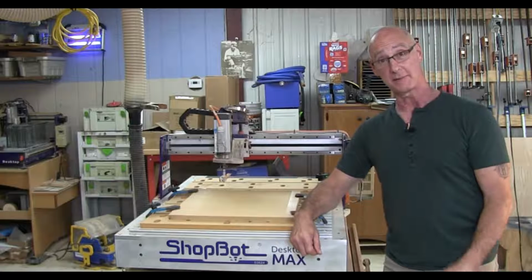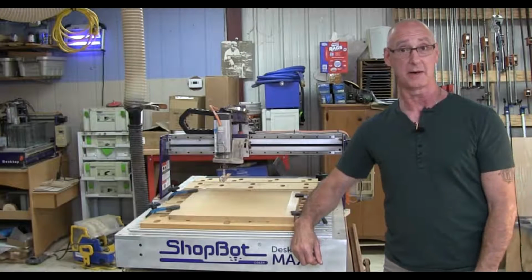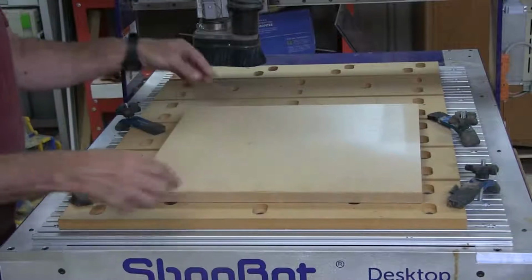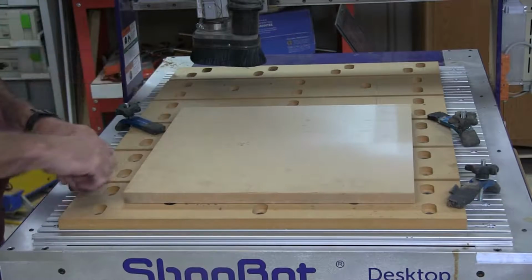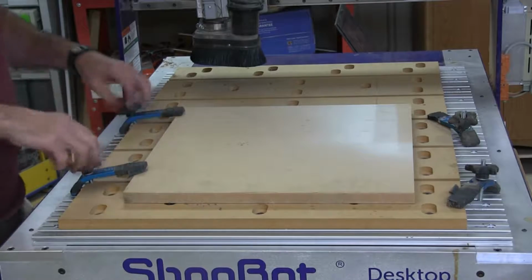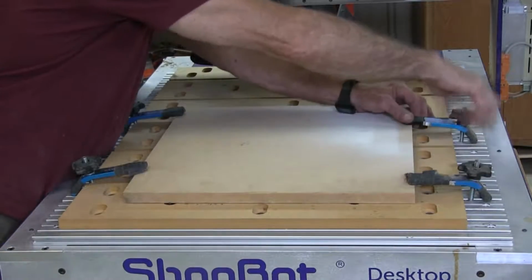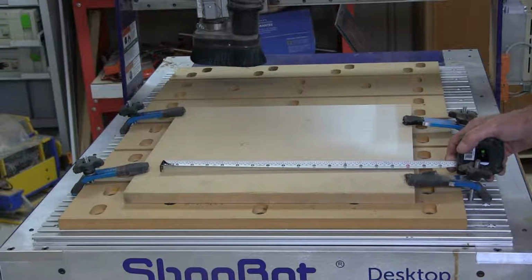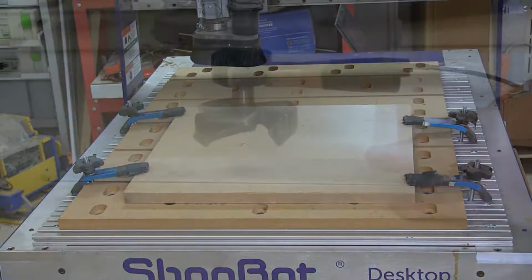Before you can use a drag knife to cut leather on your CNC, there are some things you've got to do to get the machine ready. The spoilboard used with the drag knife needs to be dead flat. I install a sacrificial 3/4 inch MDF board over my T-track table. Measure the usable area of that board and create a pocket toolpath that size.